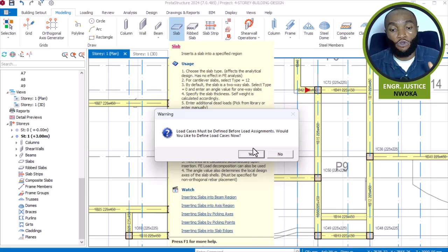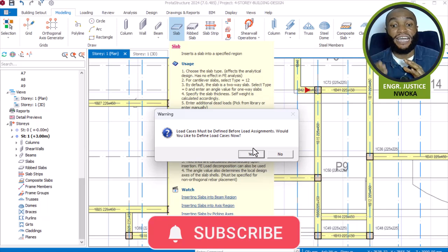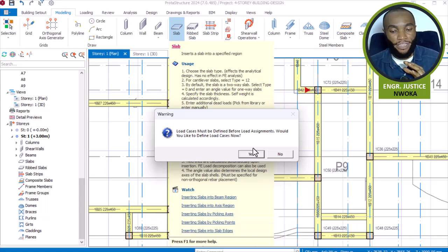In this case, this building is more than 10 meters high, since some parts are 5-story and some parts are 4-story, and the headroom, which is the height of each floor, is a minimum of 3.4. So 3.4 multiplied by 5 gives almost 20 meters height of building. That's already way too high, and we are meant to apply wind load on that structure. Okay, that's fine. So with that, I will click yes.